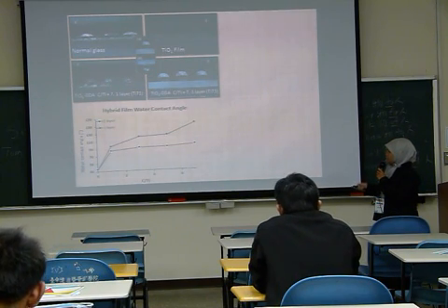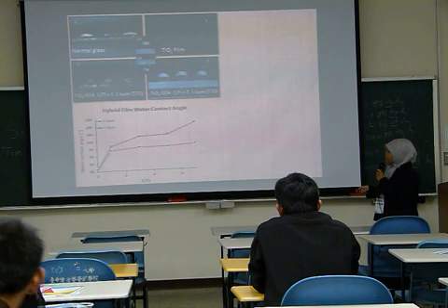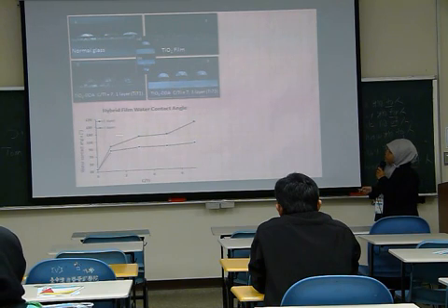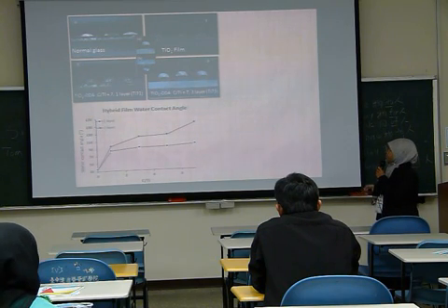It is seen that the hydrophobicity increased with the increase of composition and layer. And we can see the highest contact angle here is more than 150 degrees. So this highest composition has the superhydrophobic property.